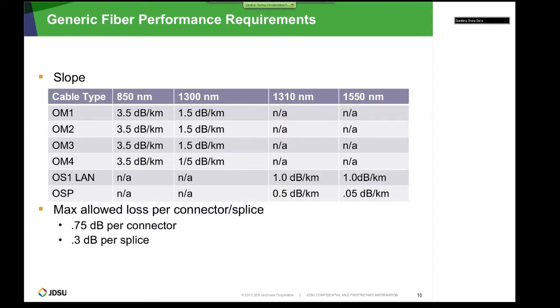Here we are going to speak about single mode cables. Single mode cables have much lower attenuation, meaning insertion loss per kilometer, in comparison with the multi-mode. We are speaking about 1 dB per kilometer, even less. Here this is a typing error. Yeah, it must be. It should be 0.2, 0.3 maximum.